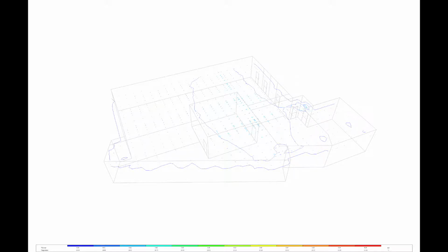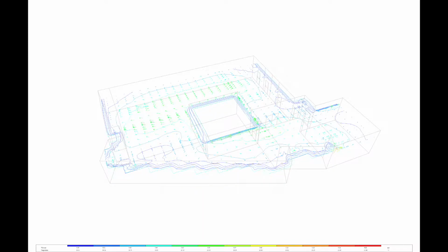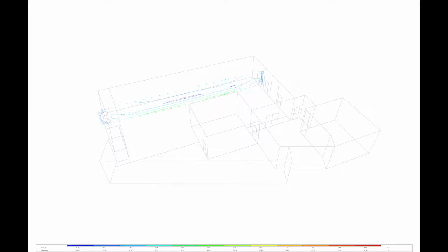The ground floor shows slow air current moving from the sides to the middle at the floor level and the opposite at the ceiling level. The main spaces in the first floor exhibit faster currents of almost similar patterns, and currents from the left side are stronger here than the ones in the ground floor due to the window that doesn't exist there.